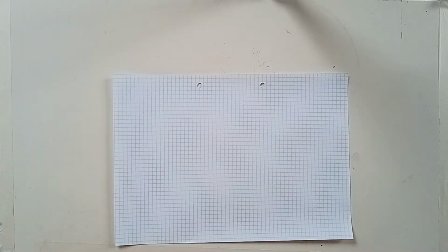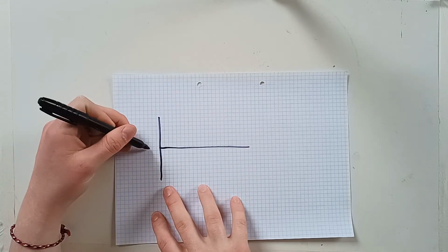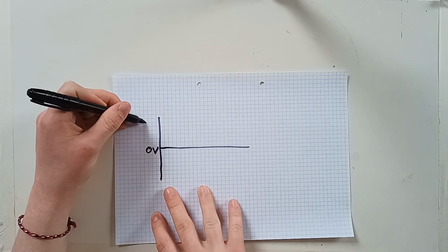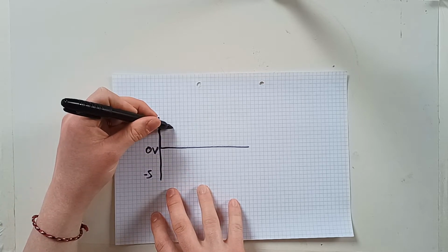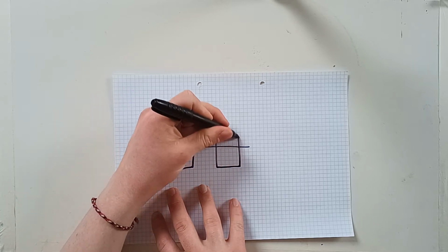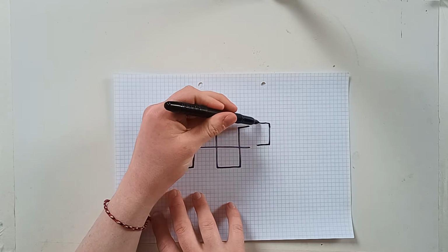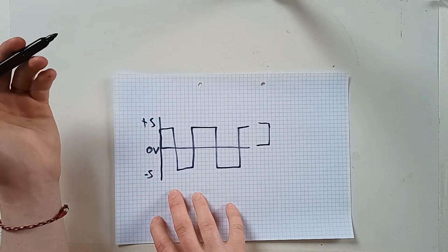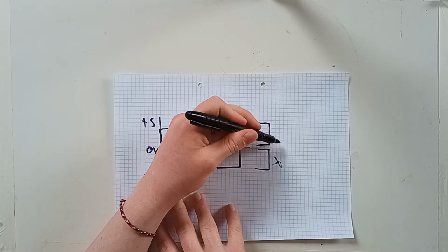But in order to get that 0.7 volts, because we would be dealing with an alternating current, which swings around 0 volts, and let's say +5 and -5 volts, and we'll go with just a square wave oscillation again, then that would mean that this top half of our signal could pass through, but this bottom half would be cut off.